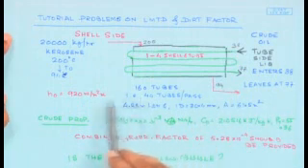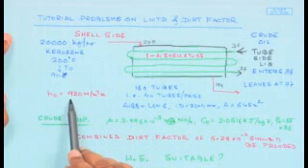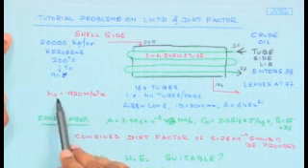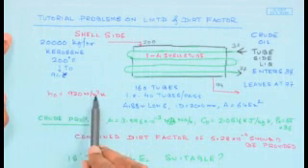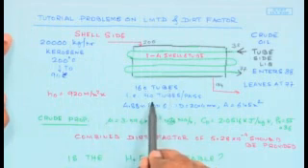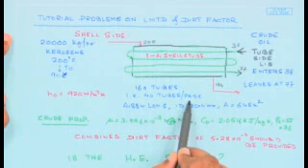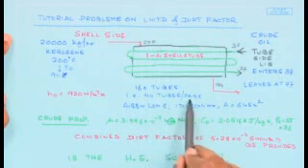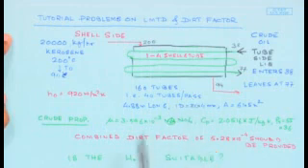It has been mentioned that the heat transfer coefficient on the shell side, which is h_o, is 920 watt per meter square Kelvin. There are a total of 160 tubes, that means 40 tubes per pass. That is the number of tubes per pass which is present in the shell and tube heat exchanger.